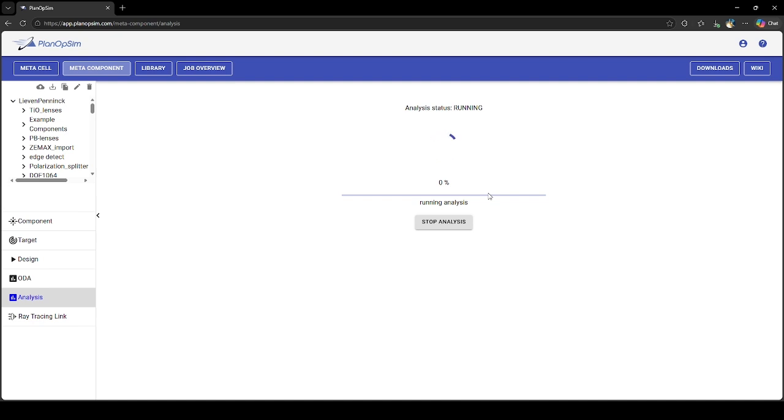As I'm sure you're well aware of, full wave calculations are limited and very time consuming. So they're limited to only a few tens of wavelengths, maybe hundreds of wavelengths in size, before they become extremely time-consuming, or just run your machines out of memory, even if you're using very powerful machines. So in order to simulate practical metasurface sizes, we have to rely on approximations, because even 1 millimeter size, which is a tiny component for a human, it's an enormous component for a full wave calculation.